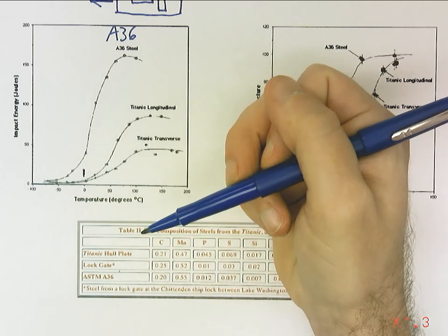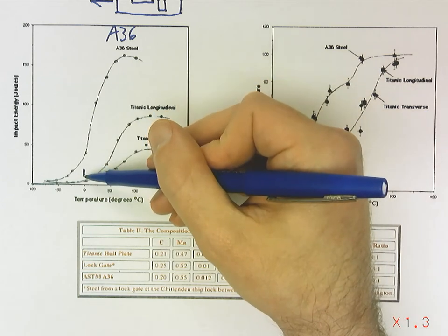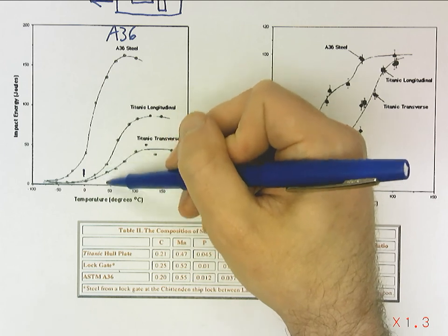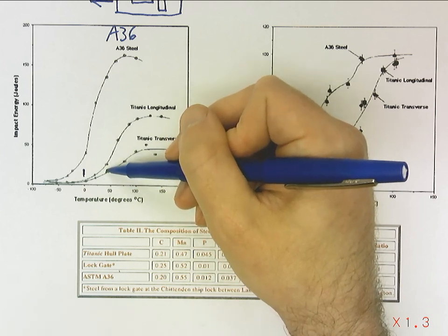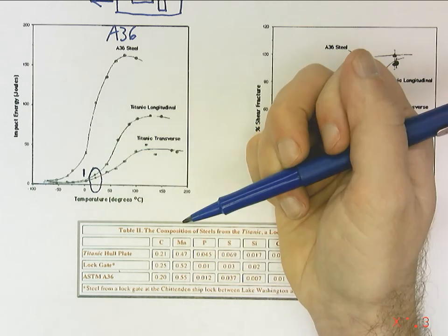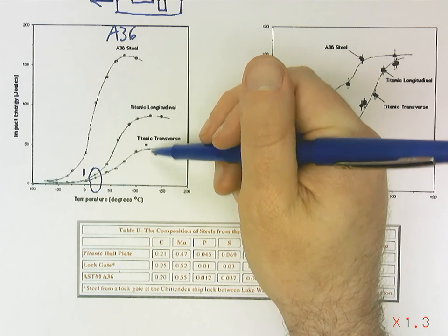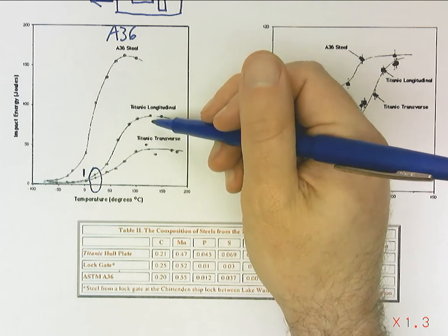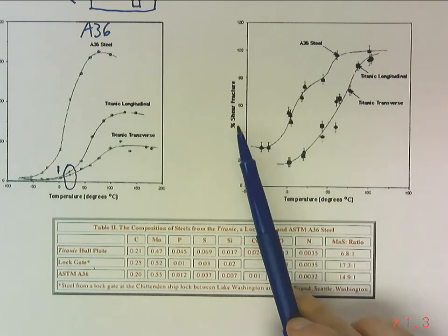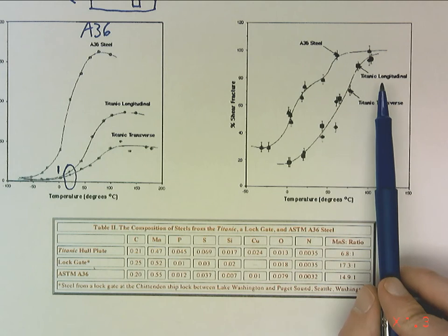Freezing point of water, the Atlantic Ocean is not at the freezing point, but if you've got icebergs rolling around in it, you're not up here at room temperature either, right? So we are looking at Titanic steel that was probably down here in port. It was probably up here during manufacture. It's up here. We're past our ductile to brittle transition. Here's our percentage of shear fracture done on a separate graph.